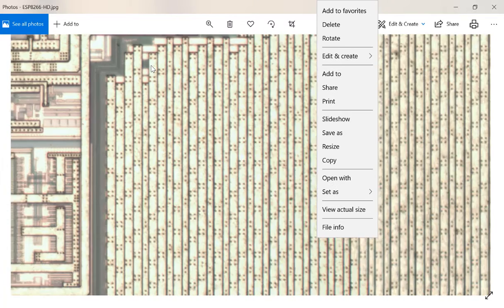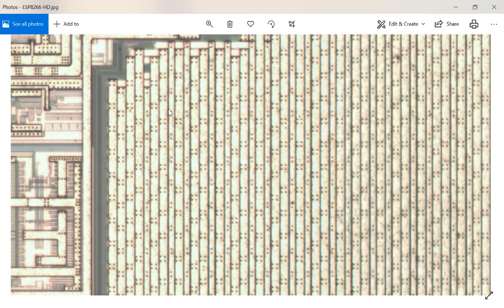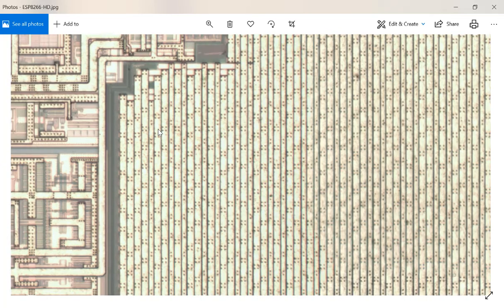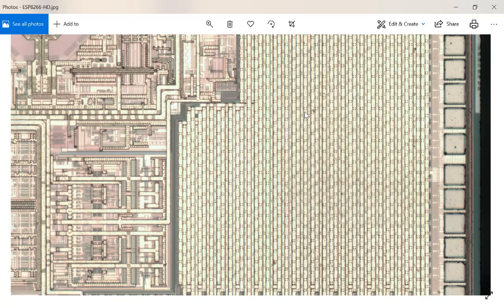So these dots are vias. Since you can see these traces super clearly, they are actually the top metal layer. It's not necessarily a metal strip, because I'm pretty sure, this is 40 nanometer technology, so they may have like 5-6 layers of metals, I don't know. But they have the metal layers on the top like this for what?